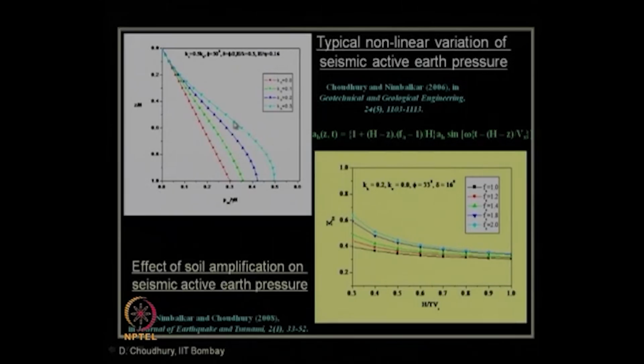So, that gives us the exact position where, and what amount of, reinforcement should be provided, when we are trying to construct and design a reinforced soil wall, or an RCC rigid retaining wall. That is clear from these results, which is not available in the pseudostatic approach.